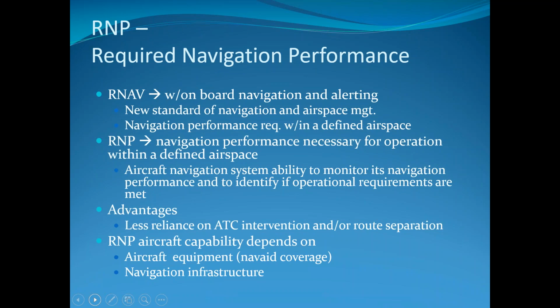You see them a lot up in Alaska, in areas where you're flying down canyons and channels, things like that, where there's a lot of terrain around that you have to navigate around, and they don't have a lot of ground-based nav aids up there. So that's what RNP is. It's pretty much the best type of satellite approach performance that you can get. So that would be listed with satellite-based under the precision category.